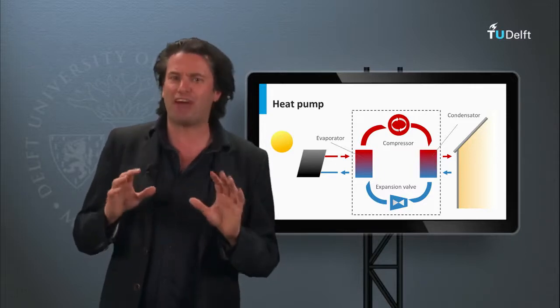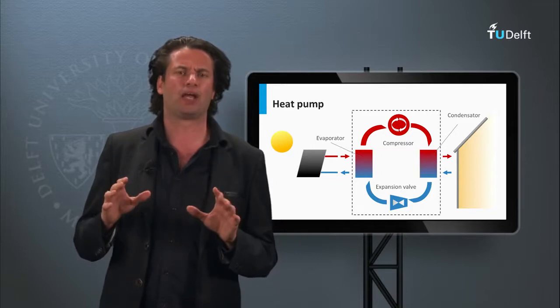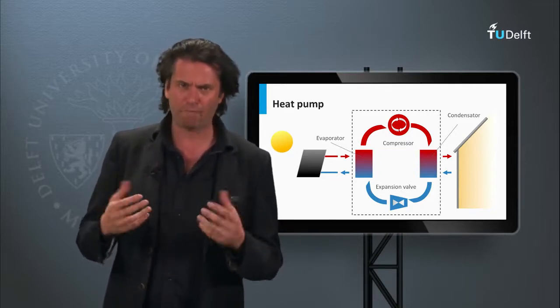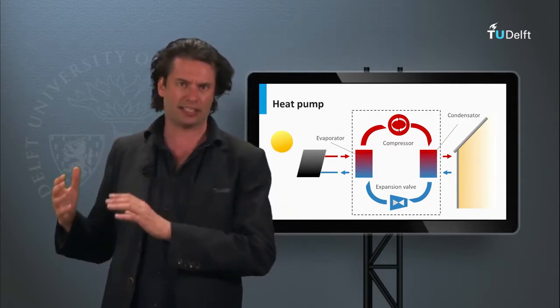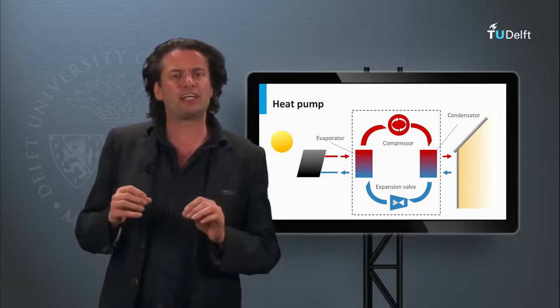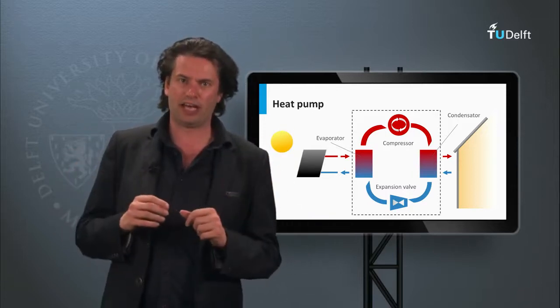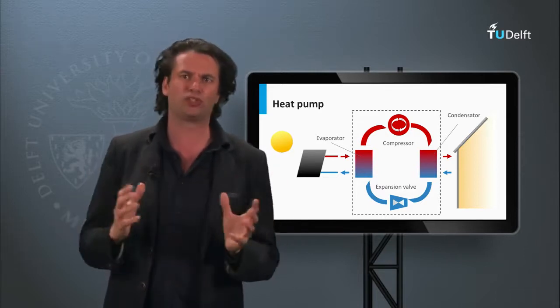One of the most famous active solar water heating systems is heat pumps. Heat pumps use mechanical energy to transfer thermal energy from a source at a lower temperature to a sink at a higher temperature. The concept is that the working fluid of the pump evaporates in the collector, and the condenser of the pump is a heat exchanger wrapped around the storage tank.